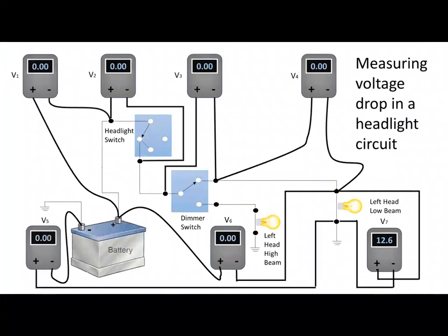Be sure the battery is fully charged and that the battery terminals are clean and tight before any light diagnosis. When the engine is running, charging circuit voltage is supplied to all the lights that are turned on. Therefore, improper charging circuit operation affects the light circuits.